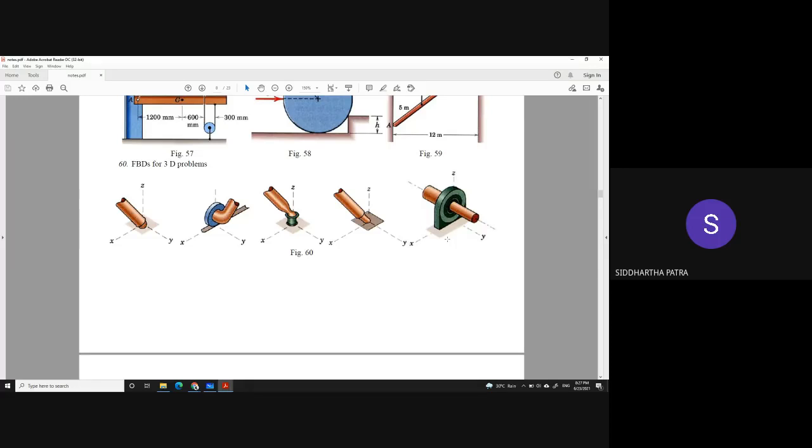The green one is actually the part of the ground. It is fixed to the ground. So can this rigid body translate in x? No, sir. Okay, so there is Rx. Sir, it will have 5 reactions except the moment about y.